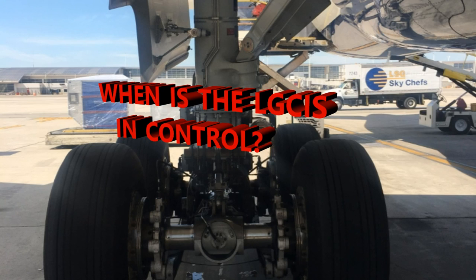So they have the two sides, and they're not operating at the same time. You're going to have just one side controlling the system at any given time. And that's going to be monitored as well. Besides controlling the system, there's going to be a continuous monitoring through the Autoflight Data Exchange Network. So if one side is not going to work, then the other side is going to become active.